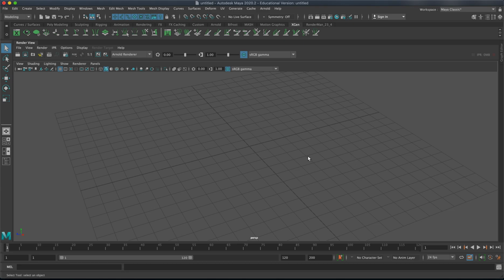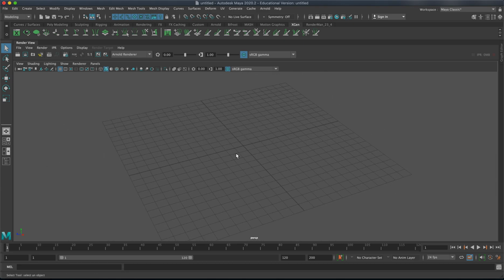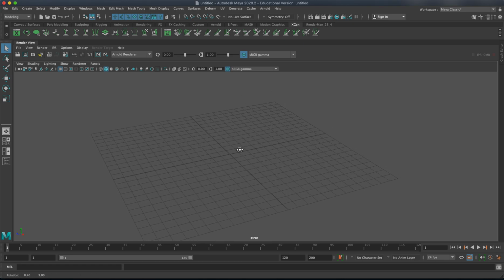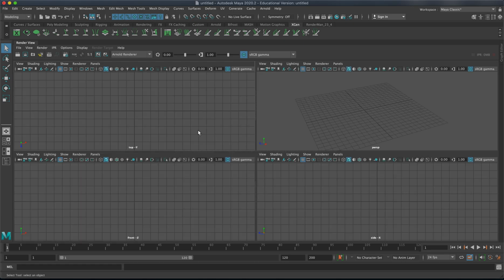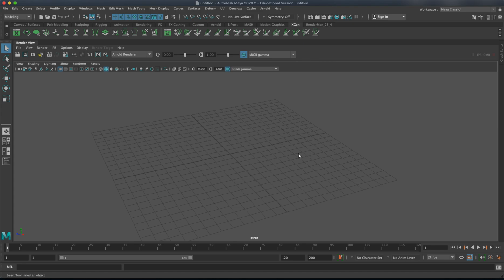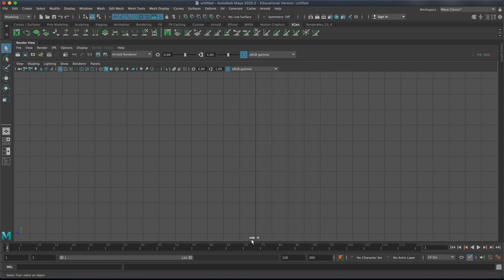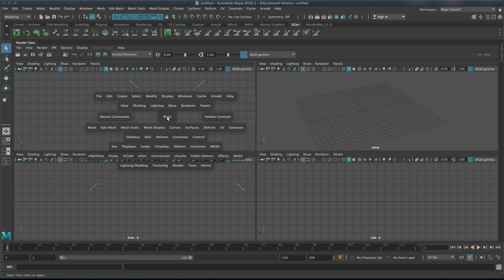And you'll really need to practice that so we can swing around when we're modeling or rigging, and also prepping files to get into Unity. Another hotkey that we're going to learn is Spacebar. If I hit Spacebar once, it'll go from perspective to ortho to my top, front, and side view. Wherever my cursor is, if I hit Spacebar again, it'll go to the side view, front view, and I hit Spacebar again, it'll go to the top view.